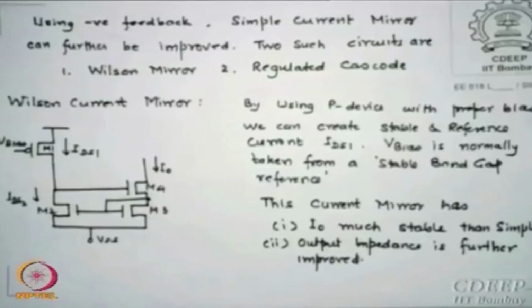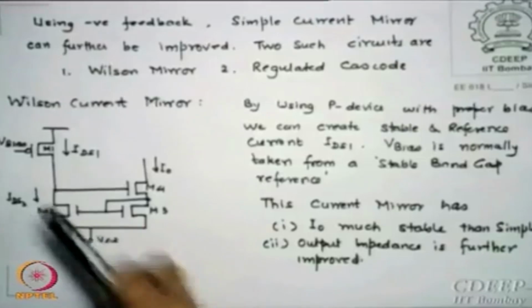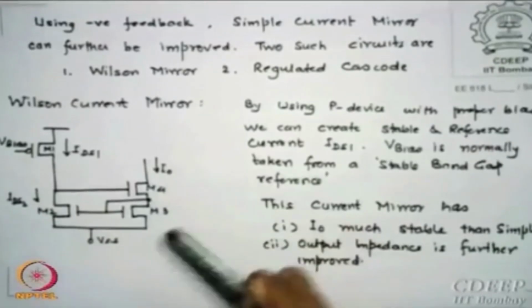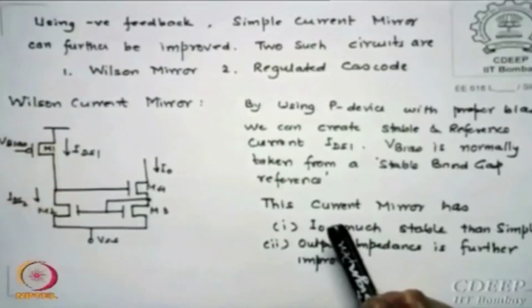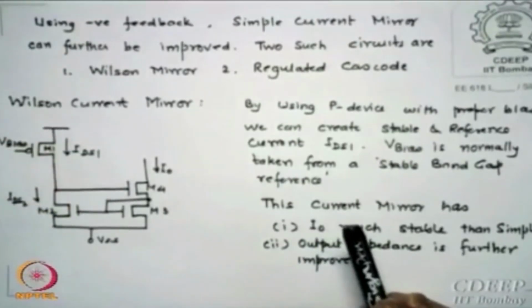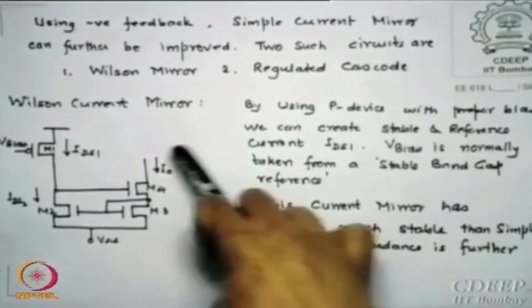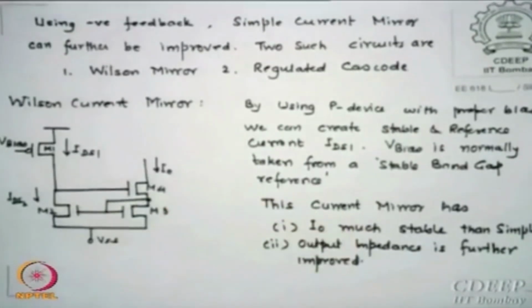Because two currents cannot flow, but now I am forcing this to increase, which means this voltage must go down because the IR drop will go down, so that this VGS falls. So this current will reduce then. Is that correct? Because we say IDS1 has to be IDS2. Is that clear? So how a feedback will force that issue, that only IDS1 current can flow down even if there is a variation in I0, is what I said, and therefore I0 will become constant independent of anything. This is called Wilson's feedback system. These are simple statements, nothing very great.